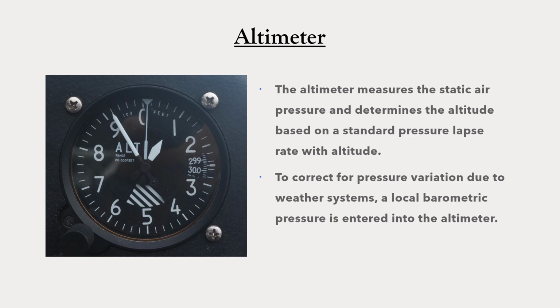Typically, that's the airfield that you took off from. If you're doing cross country, you may have to make adjustments to that as you move from place to place. This can be set either by obtaining this information from a weather source, or just turning this dial while you're on the ground at a known altitude to make the altimeter read the correct altitude for the place you're taking off from.